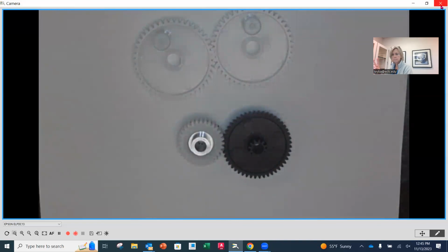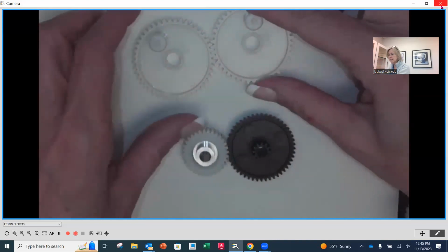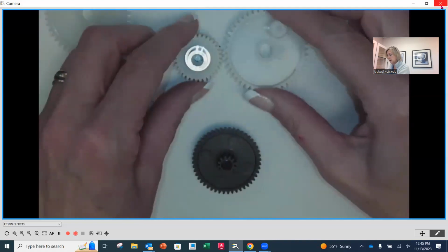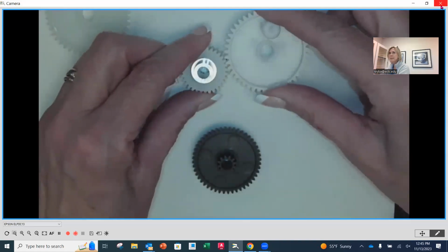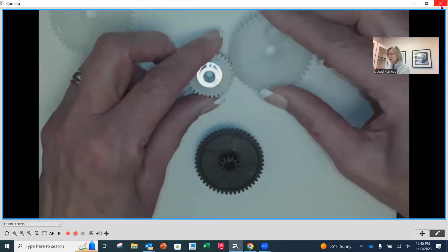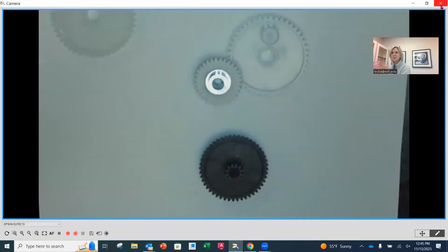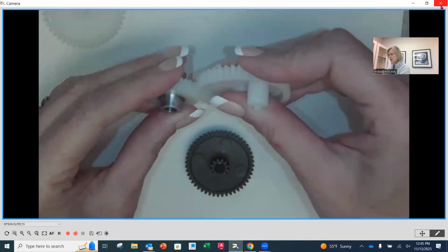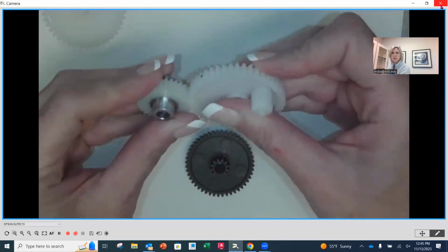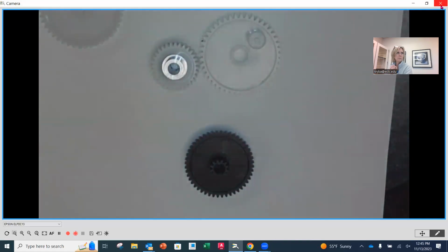Always. Now, these look pretty darn close. If I take these apart and I try to put them together, you will feel the difference right away. And it won't take long. They'll start to wear into each other. You'll start losing material between the two because they'll be shaving each other off. And then all of a sudden, you are going to find that your gears are no longer going to work the way they're supposed to, and they'll prematurely wear.